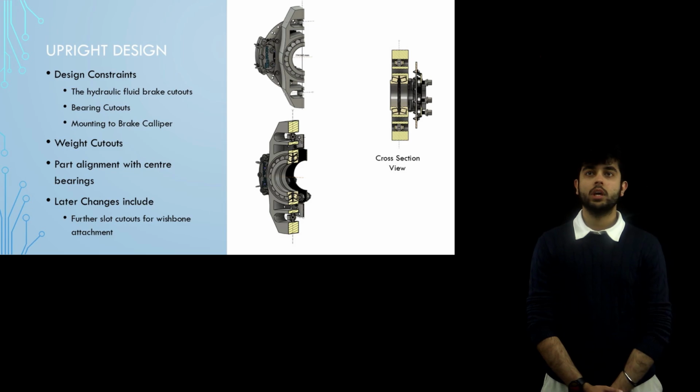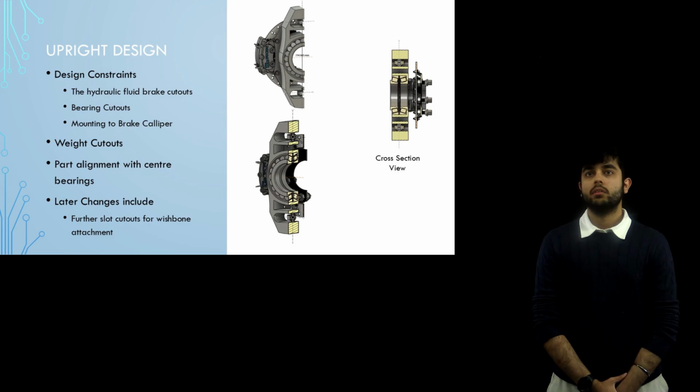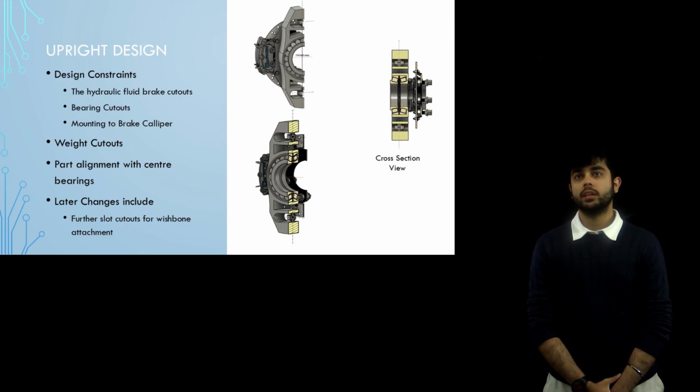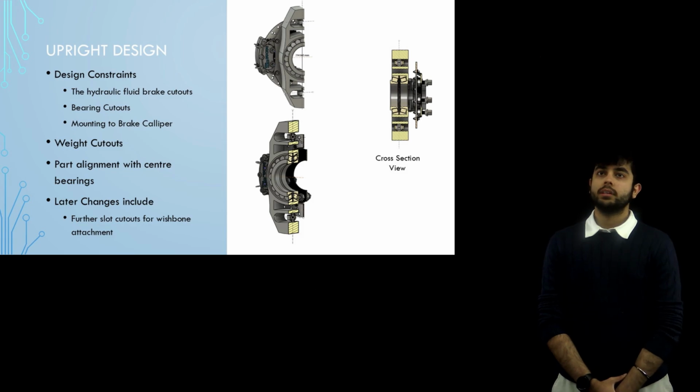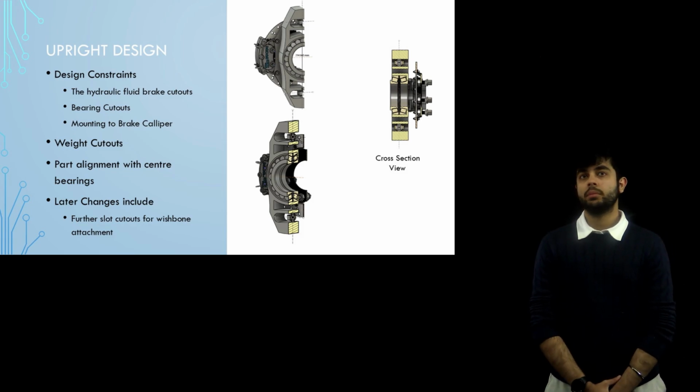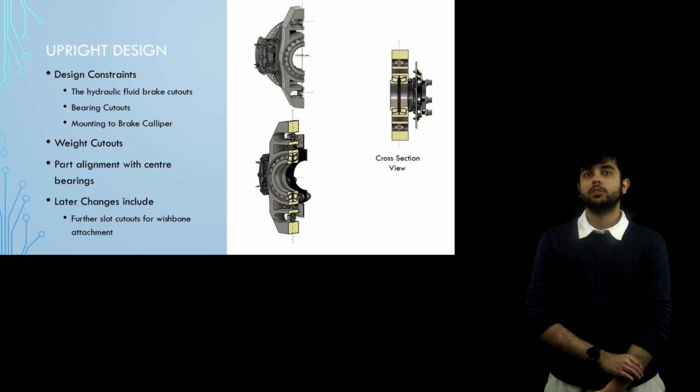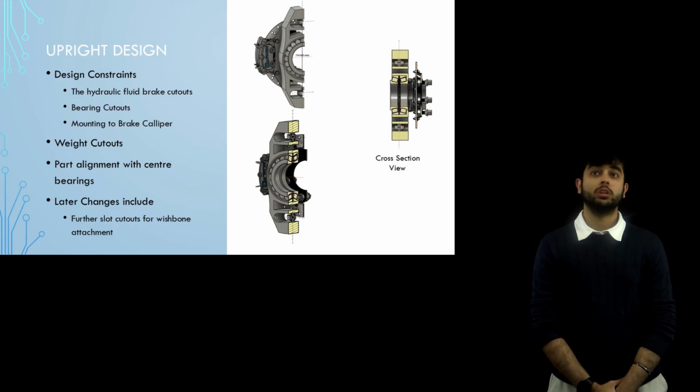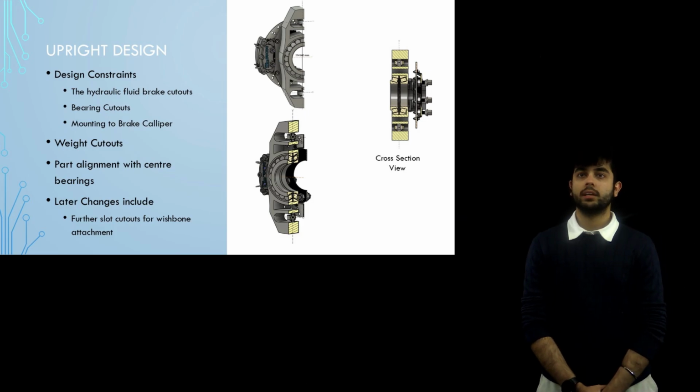We began the design by selecting the inner and outer bearing axis lines as our main datum features. Revolving the geometry around these lines gave us a strong foundation for symmetry and accurate placement of all mounting interfaces. From this base, we carefully constructed the upright using reference edges and bearing center projections to ensure proper alignment and structural clarity. The final design integrated all major suspension mounting points, which included the upper and lower wishbone pickups, which handle vertical and lateral loads, the tie rod interface, which allows for fine-tuning of steering angles, and the strut rod mounts, which manage longitudinal loads during braking and acceleration.